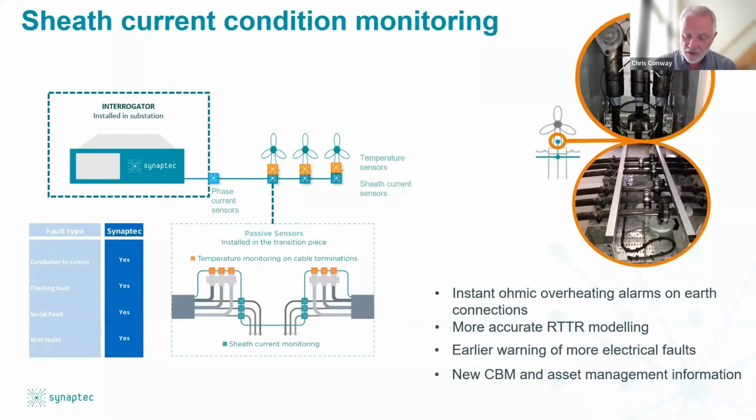There could be a symptom of cable termination degradation, and knowing those changes in impedance and resistance and how it's reflected in changes in current enables us to distinguish or categorize between these pending faults.